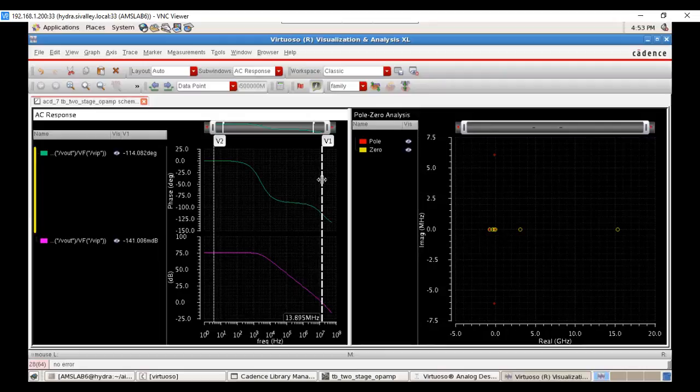So generally for any amplifier design, whether it's single stage or two stage, the phase margin that we take as a design parameter, is that for open loop or closed loop, or are they specified differently? As far as I know, we generally define it for open loop, not for the closed loop. So closed loop is user dependent, right? Whether the user wants unity gain closed loop or some other closed loop gain, that is left to him. We don't know exactly what requirement the user has.